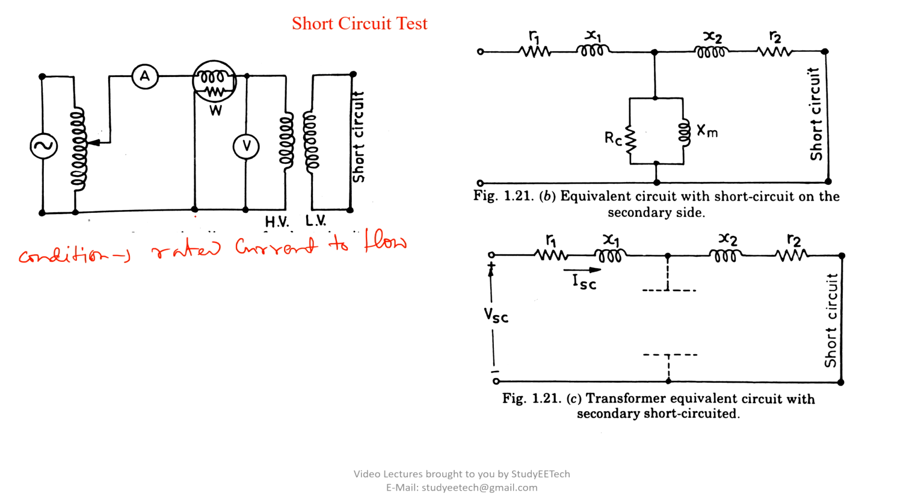Okay, so how is that possible? Look what I have made. This is E2 here. If we would connect some impedance or load, there would have been V2, but V2 is 0 here. So we can say I2 is only E2 by Z2, and previously it would be E2 minus V2, but V2 is 0 here.